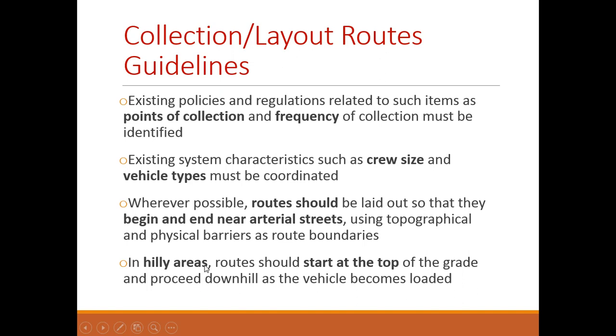Additionally, in hilly areas, routes should start at the top of the grade, the top of the hill, and proceed downhill as the vehicle becomes loaded. Logically, as you begin to fill the vehicle, it will become heavier and heavier. So it would make sense for you to move in a downhill direction so that your movement could be facilitated by gravity.